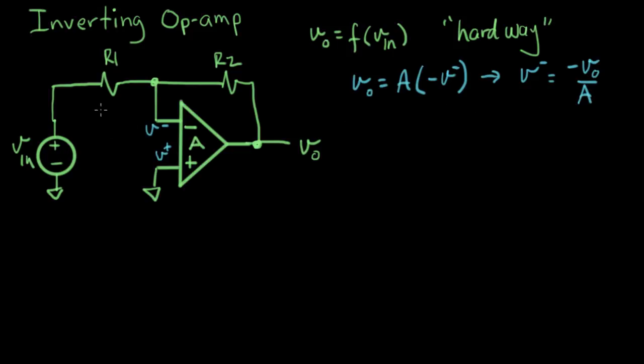So what else can we write for this circuit? Okay, let's look at these resistors. Let's call this plus or minus VR1, and we'll call this one plus minus VR2. So there's a current flowing here, and that we'll call I. I'm just going to use Ohm's law on R1 here and write an expression for I. I equals VR1 over R1.